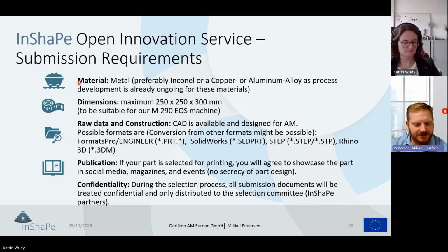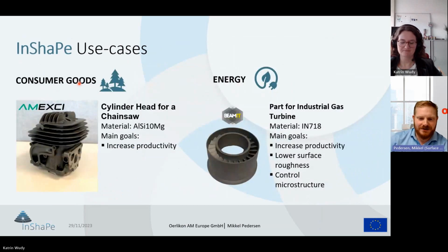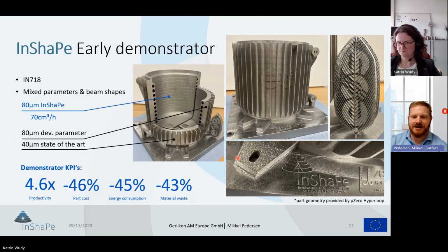You can look a little bit like it with the Beam It use case, where the goal is microstructure control, and some of that is to reduce variability. So we're not making a fundamentally new microstructure of the Inconel 718. A lot looks like what you would expect from a printed microstructure, I have to say. But we have a much more uniform microstructure, which helps on qualification and also on the part performing the same every time and the performance is expected the same. So that element, but we're not fundamentally changing how a 718 printed works.